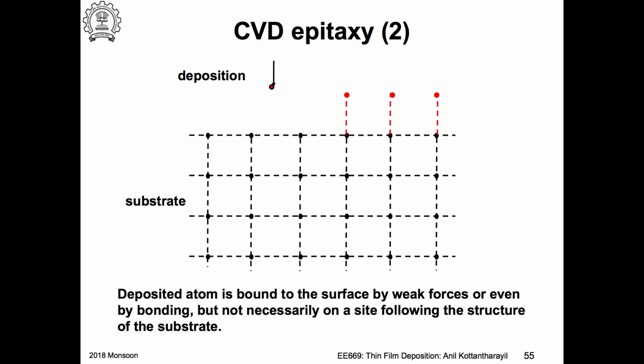So in the last lecture, we started reviewing some examples of CVD. We'll continue that, and we were discussing the epitaxial growth of silicon. We briefly discussed the difference between amorphous silicon deposition, polycrystalline silicon, and monocrystalline silicon. A very critical parameter here is actually the temperature. And we have briefly discussed why you need higher temperature for the growth of crystalline forms.